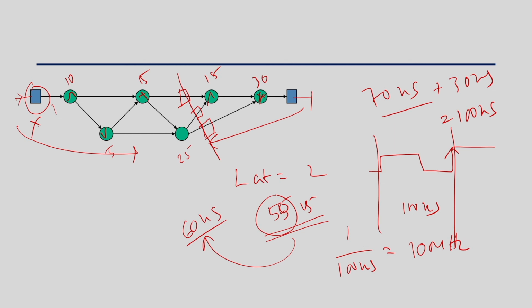Sometimes this circuit might have a million gates, and retiming is usually an order of n cube algorithm. So, that may be too complex to apply to a complete circuit, but I can always find a small part of the circuit where it is causing a problem, and then I can apply retiming locally, right. So, you can apply a divide and conquer kind of approach, taking the circuit part by part and applying retiming there. So, that is local retiming, and the third one is called peripheral retiming.